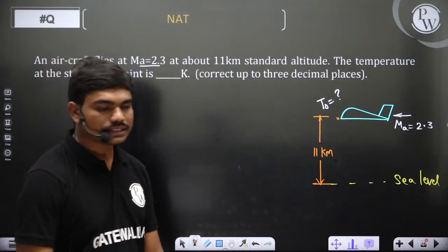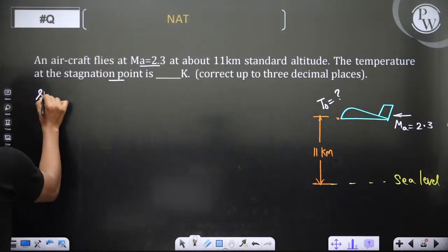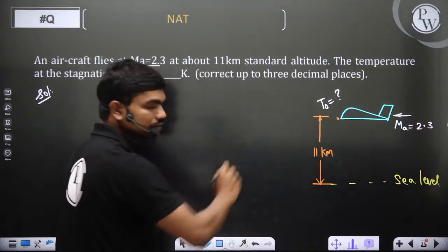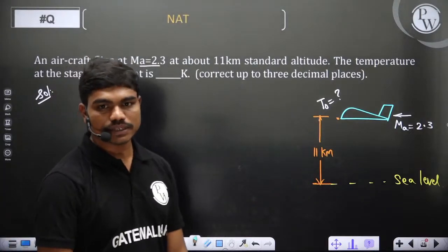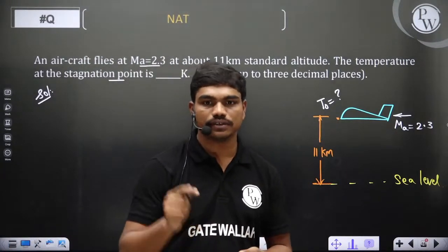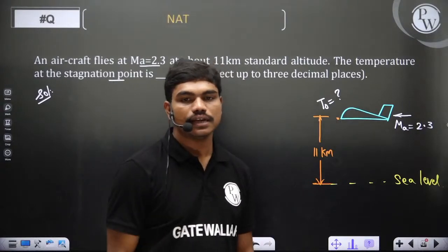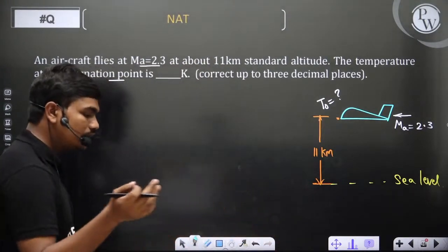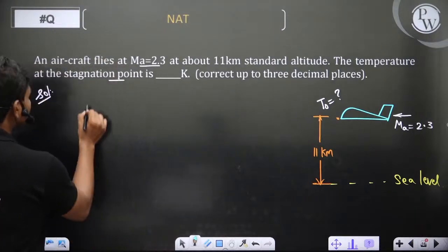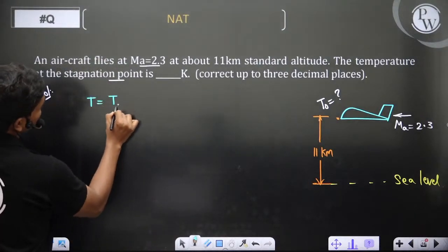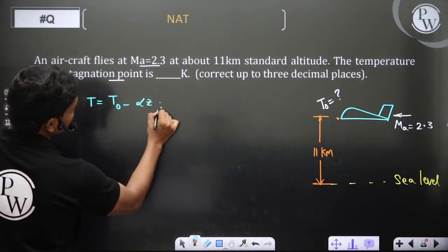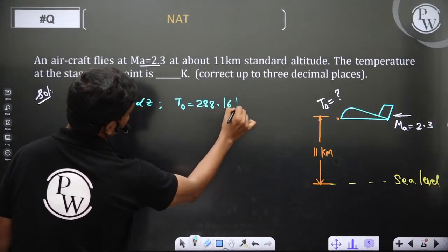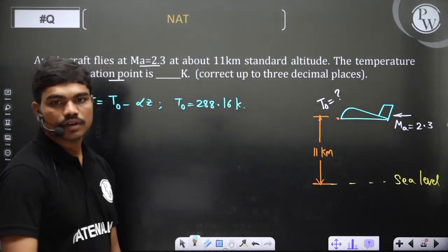Let's see how we can do this. Normally in the atmosphere, we have the temperature variation, which I gave you in fluid mechanics. You remember, the pressure variation in the atmosphere I told you varies exponentially, like a power law kind of model, in fluid statics. So T at any elevation is given by T0 minus alpha z, where T0 is roughly 288.16 Kelvin, normally 15 degrees Celsius.